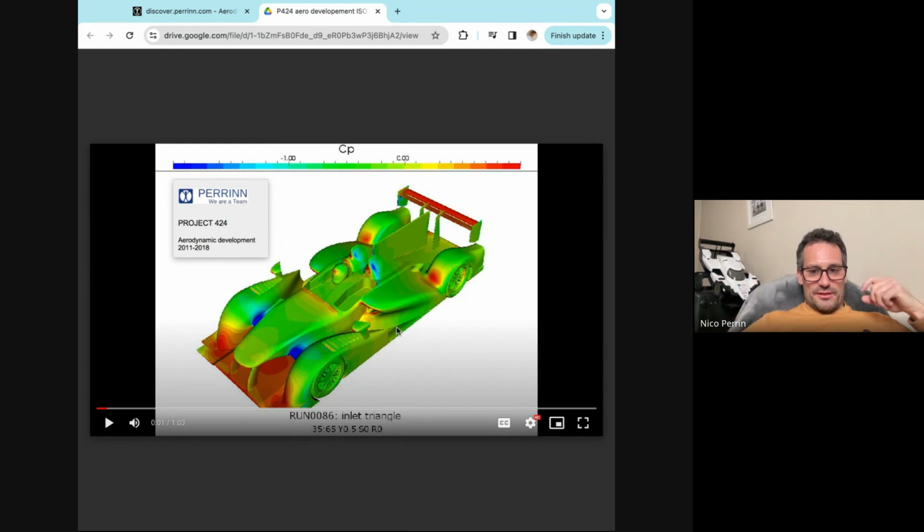Because you can imagine, say I want to just raise the side pods by 25 millimeter, which is typically the step I would do to see the sensitivity of that. It was very complicated to modify these surfaces. And remember, I was trying to do 3 tests per day.